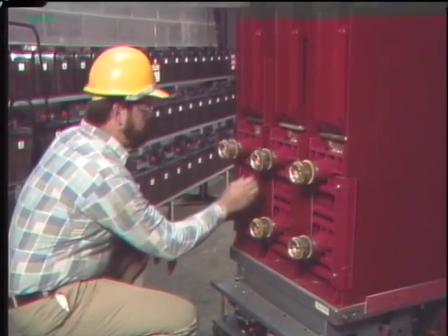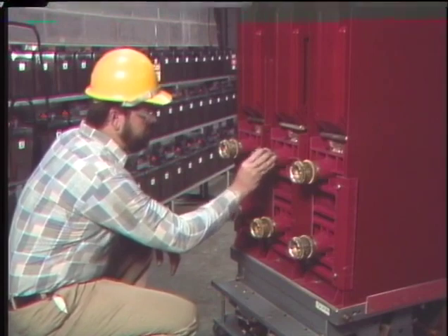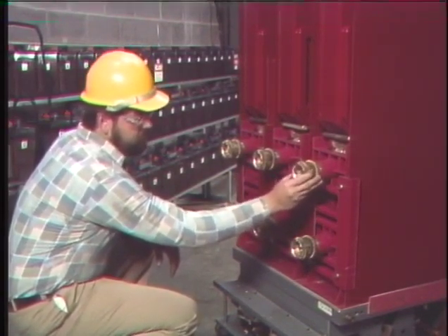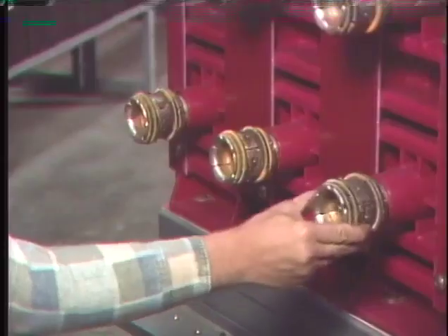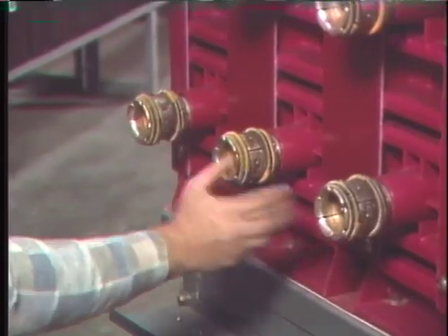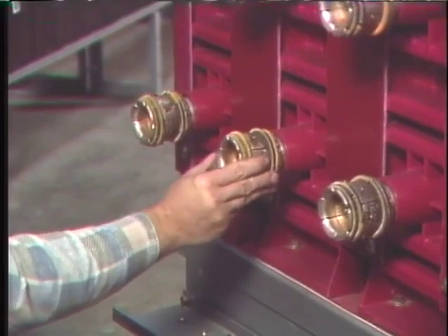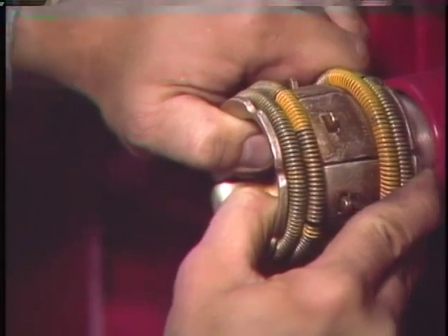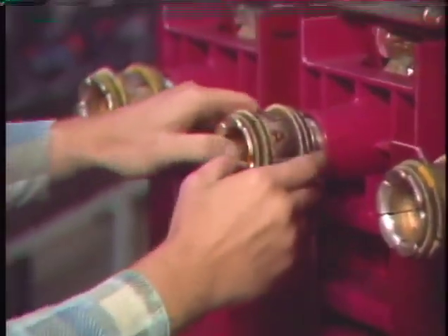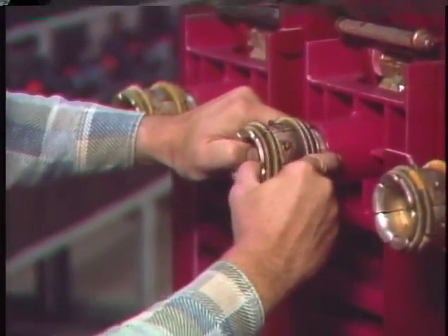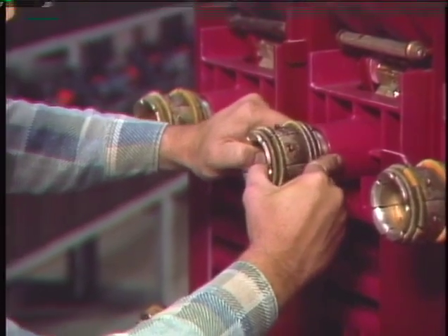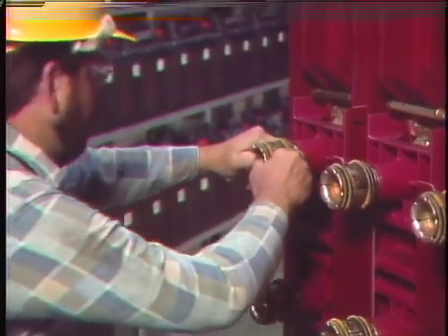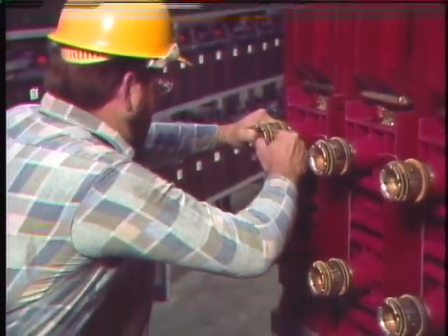Some maintenance tasks on the breakers themselves are also the same for both air magnetic breakers and vacuum breakers. The breaker bus and line connections are checked for freedom of movement. It's important that they can swivel to align themselves with the connections in the cabinet. Retaining springs are checked for proper tension. Tight springs help ensure tight connections. Loose connections can cause high resistance and overheating. Any springs that have lost their tension should be replaced.